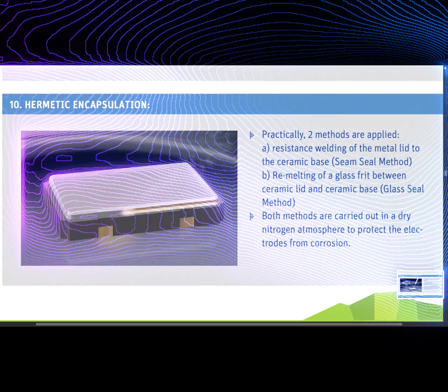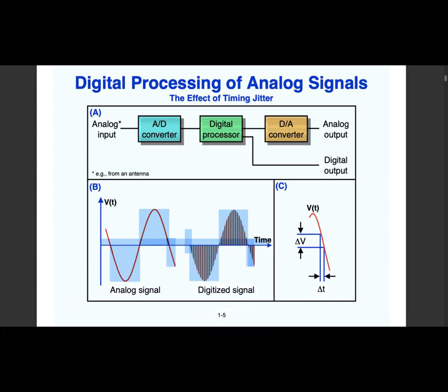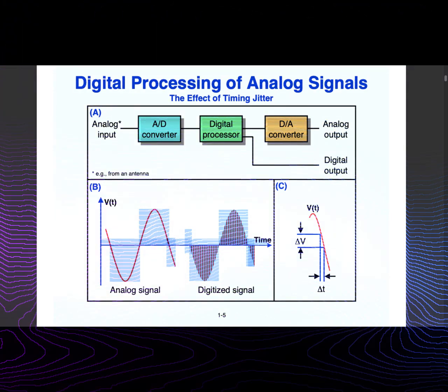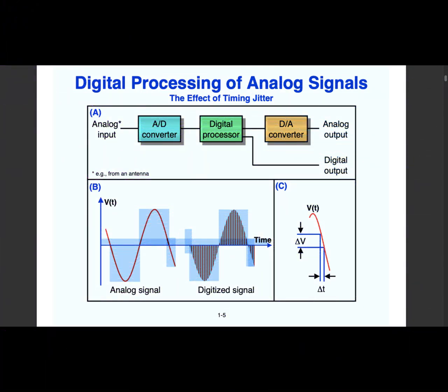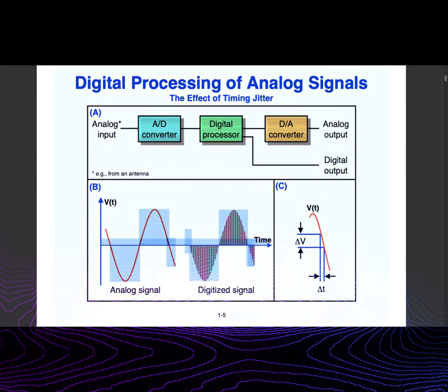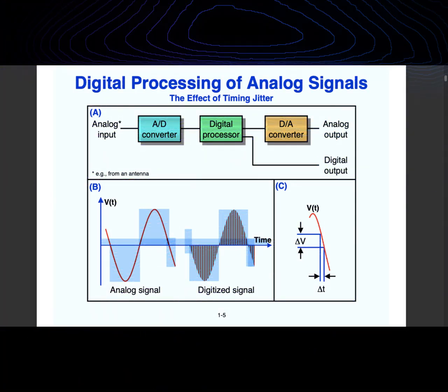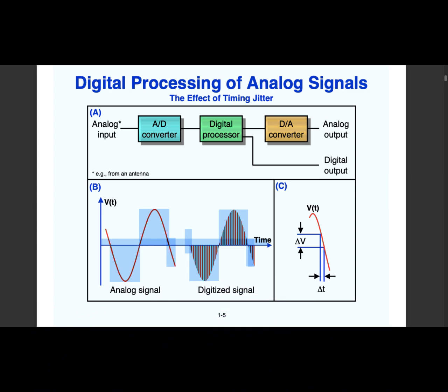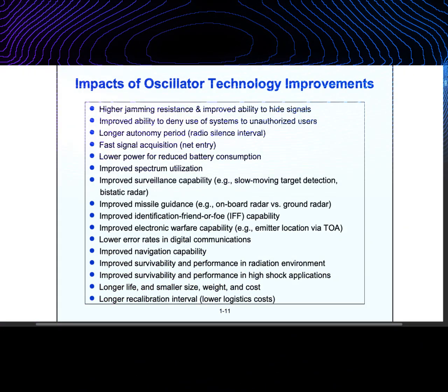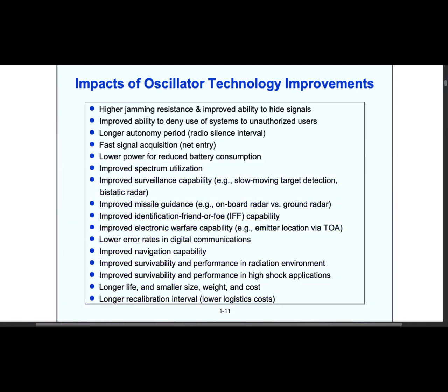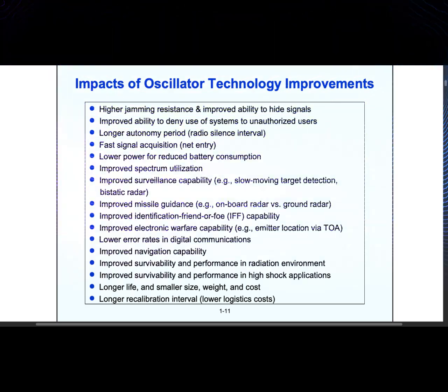When an alternating voltage is applied to the electrodes, the piezoelectric effect stimulates a mechanical vibration, whereby the resonant frequency is defined by the blank thickness. In simple words, we can say that the inverse piezoelectric effect is used to stimulate the resonance of the crystal, and at the same time, the direct piezoelectric effect is used to detect the mechanical movement, ideally at resonance.